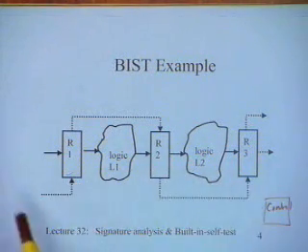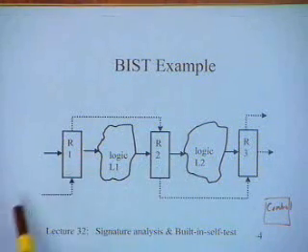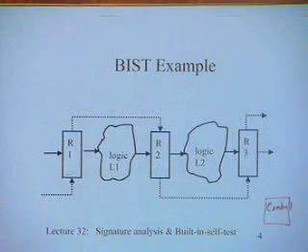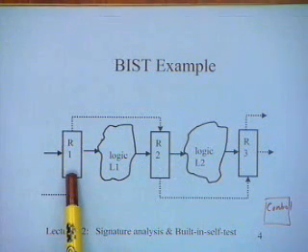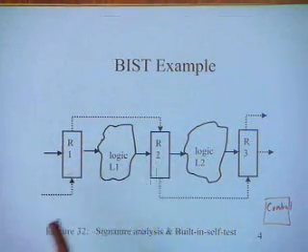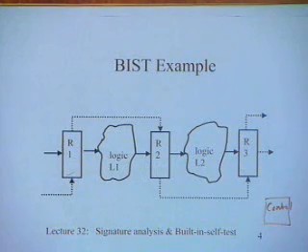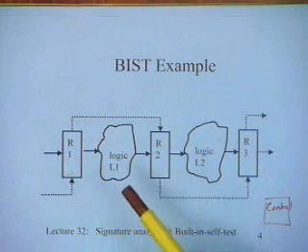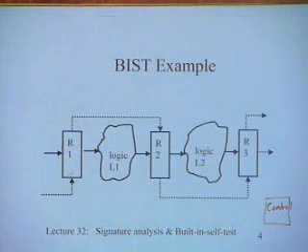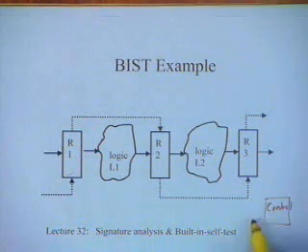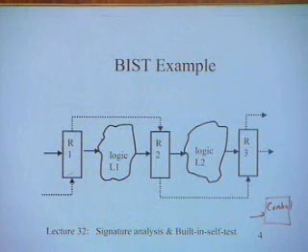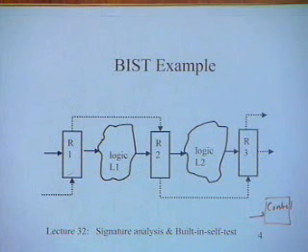But even to apply one pattern, assume that there are 1000 flip-flops, you require 1000 clocks to get the pattern into the register, and then apply it, and then another 1000 clocks to get the result out of the register. So it is much more time consuming to perform a large number of tests in that mode. For this reason, today for complex circuits, when you can afford this type of overhead for testing, almost always the built-in self-test mode is used.